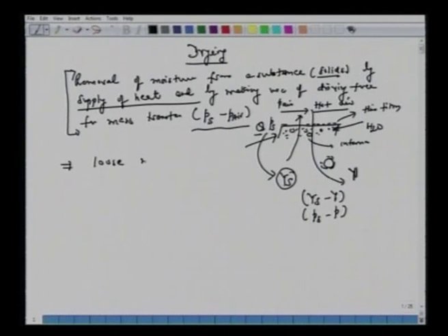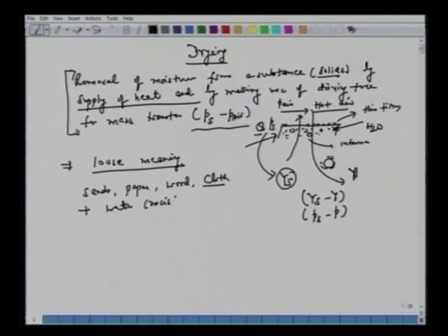So all we mean is that we have to be careful that in our context, what we are trying to say here is that the solids like sands, say paper, wood, cloth, some carbon fiber cloth, contain water or moisture. Now the type of this moisture with the sands or these solids could also be different. Maybe we talked about this in case of adsorption, that there are a lot of capillaries or pores within the solids, so moisture can be embedded inside. Alright, moisture can be inside, and some excess moisture can also be on the external solid surface.